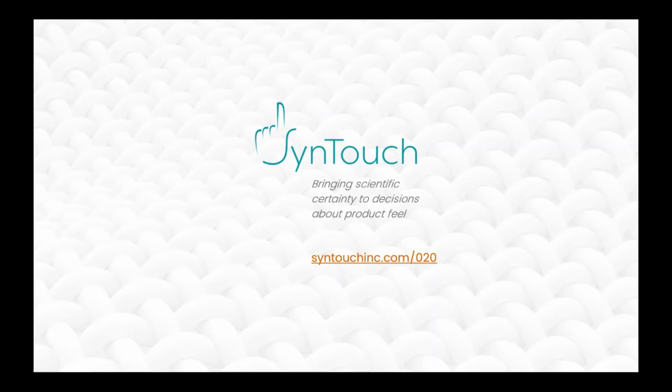We've got a question here. What's the minimum sample thickness requirement for a sample? There's no minimum per se. We've tested things as fine as different products applied to things like human hair, or a couple of microns thick in terms of paint thickness, different types of coatings used in the automotive arena. In general, we would find that samples typically range from about half to about 1 millimeter, all the way up to around 70 to 80 millimeters. Those aren't hard restrictions. We just tend to find that the majority of our samples fall within that thickness range.